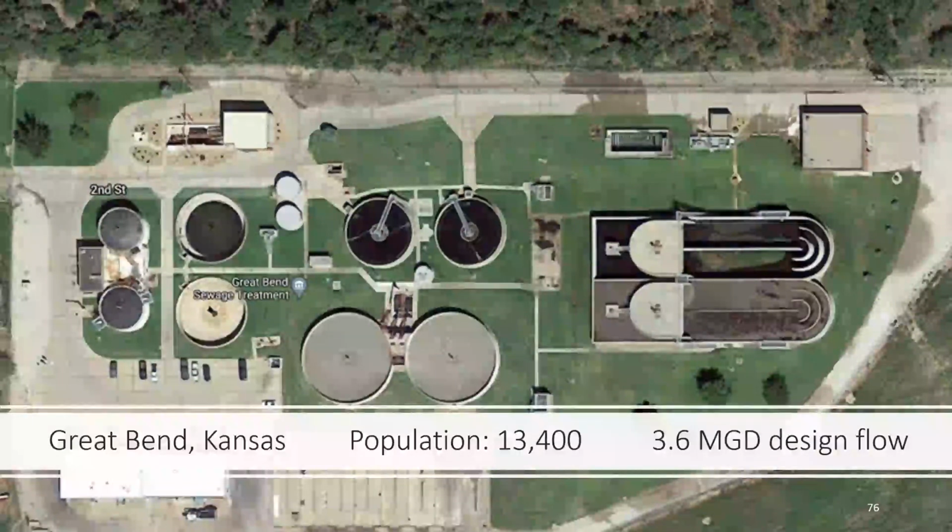So the longer the hydraulic retention time, it means the longer the wastewater is hanging around, the theoretical drop of water that comes in and then displaces another one before it comes back out again. And it means then you have more flexibility with how long those cycles can be. So at 75 minutes and 70 minutes, added together is about 2.5 hours. So if you have 2.5 hours and you have a 24-hour hydraulic retention time, that's almost 10 cycles. 10 times the air's on, 10 times the air is off.